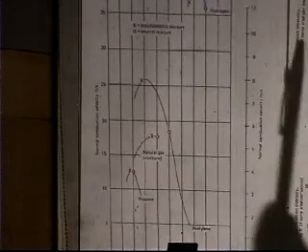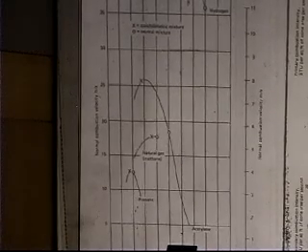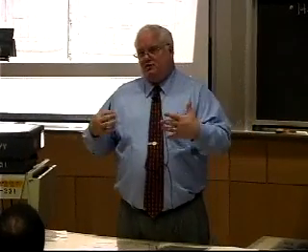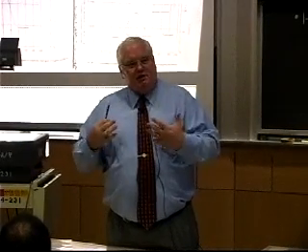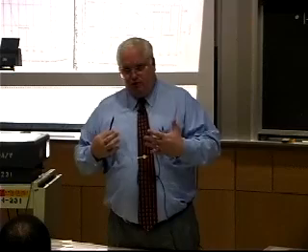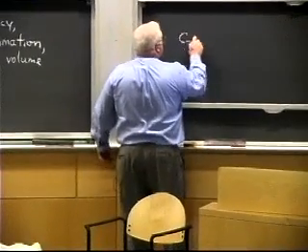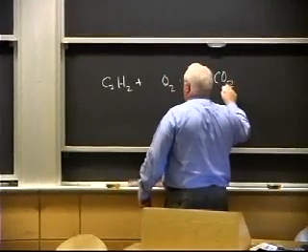It turns out because of the, what do you call it, the equilibrium constant for these reactions, you always have a little. If you mix things perfectly stoichiometric, so you have 1 mole of a hydrocarbon with the right number of moles of oxygen to get what the equation says is perfect mixing, you never get quite that complete combustion at the stoichiometric mixture, because the equilibrium constant is something like, well, if I did it for acetylene, some number of moles of oxygen goes to CO2.